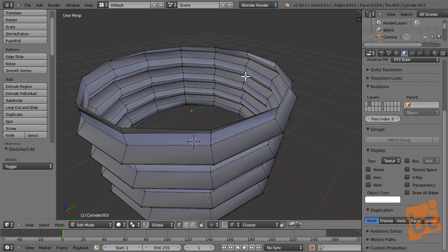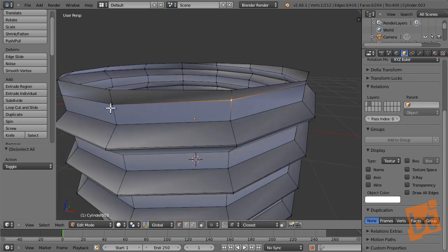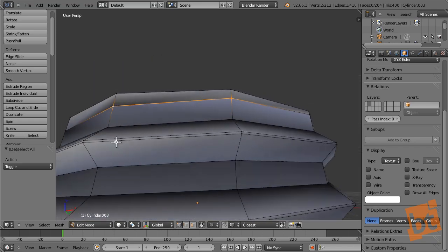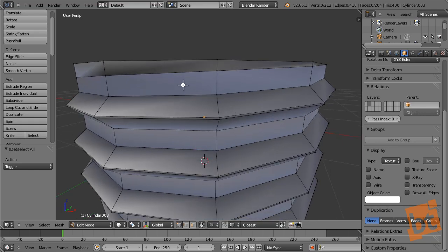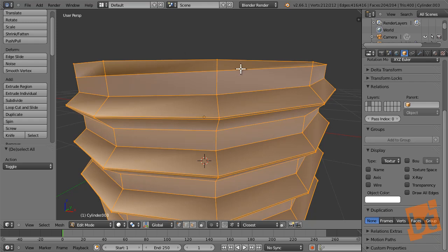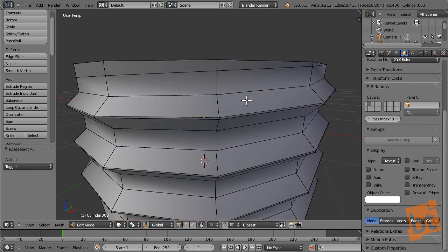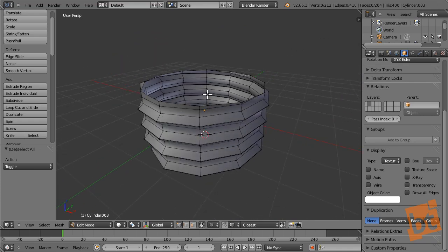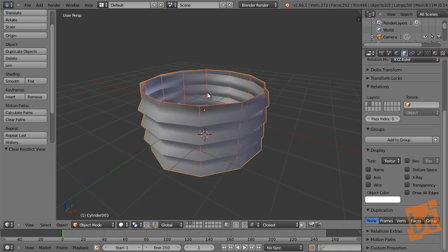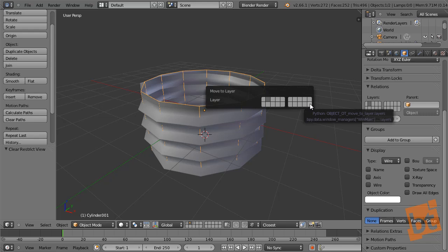Sorry. So before that, I have here, if you can see, some strange dark areas, and that is because when we weld different vertices and all that, sometimes the normals are messed up. So we select everything and press Ctrl N, and that will put the normals, all of them looking in the same direction, right? So now it's okay. So what I'm going to do is to press Alt H, select the reference, and this reference, just in case I need it in the next part for the bolt. I don't think so, but well, who knows? So I'm going to press M and send it to the last layer, which is the layer that in other software I used to call crap to hide.